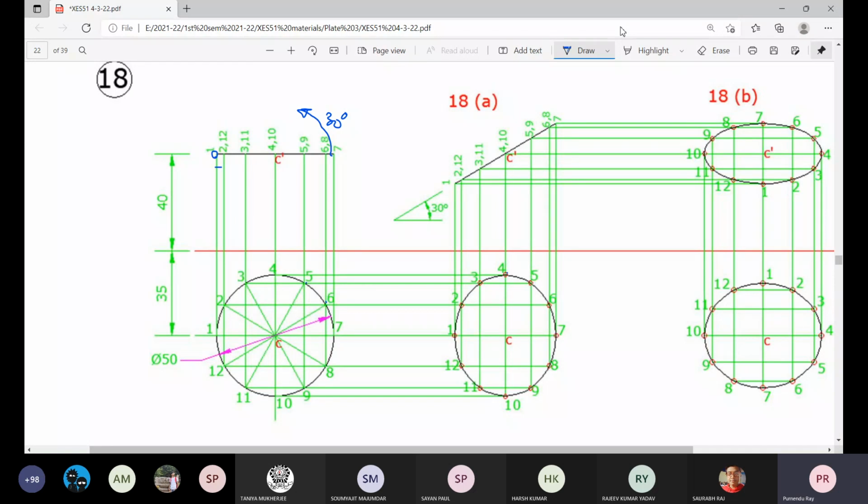And once it is that, the distance between 1 and 2, distance between 2 and 3, distance between 3 and 4, everything is satisfied here. Identically these things are there. This distance is between 2 and 3. This distance is between 3 and 4, etc. So simply use your divider compass and go on cutting these lengths. You mark it here and cut it along this 30-degree line